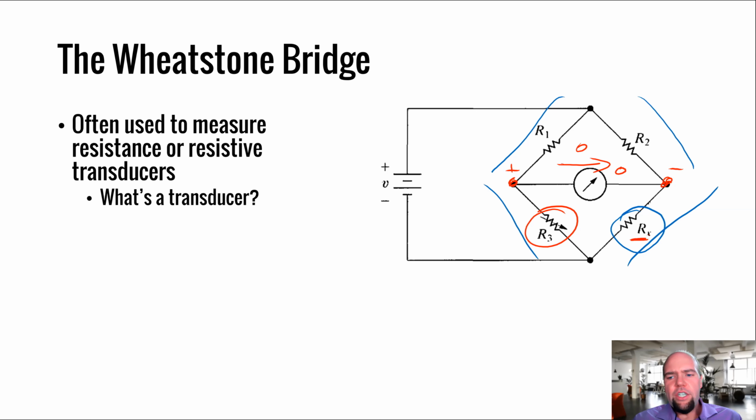But the question is, that means that the accuracy of measuring our resistor is dependent on the accuracy of our voltage supply. While sometimes we like to say you've got a 10-volt voltage supply, how much do you think it costs to actually get a 10.000 volt voltage supply with no ripple? Dead on smooth 10.00000 volts? That's going to be a very expensive voltage supply if you actually want something like that. So for doing a measurement, unless we want to spend a lot for very precise things like exactly 10-volt voltage supplies, we need to have other ways of finding resistance, assuming we have ugly supplies.